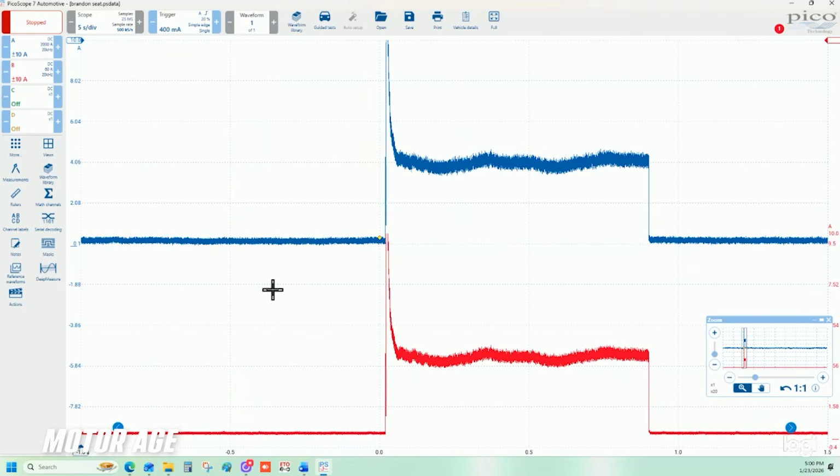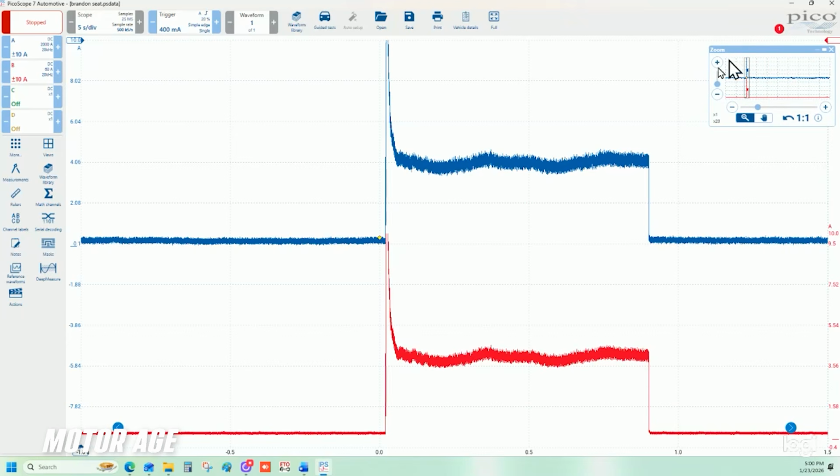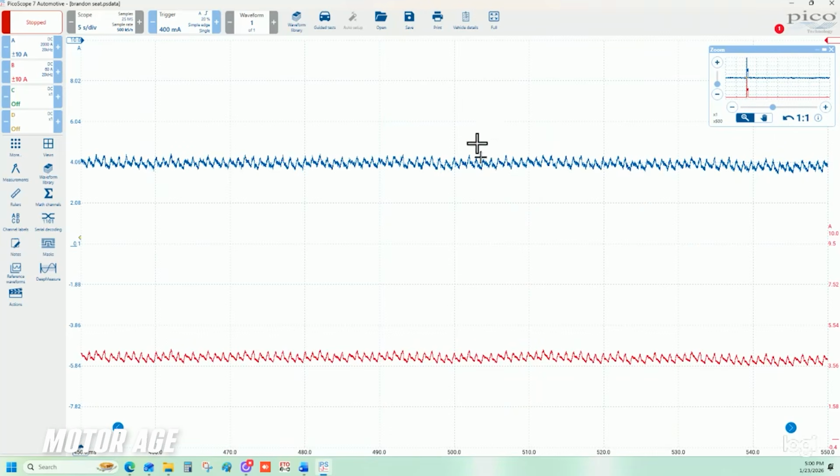Being familiar with DC motors and such, I recognize this capture as a DC motor with an inrush current of about 10 amps and running current of roughly 4 amps. Zooming in further, we can actually see the motor armature turning and it repeating itself over and over again.